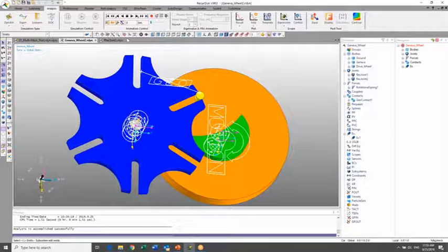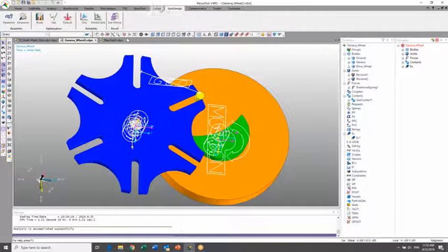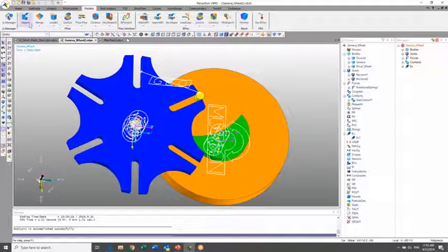There's a revolute joint and a spring, which is, I believe, just a damper at the moment. There's no spring force, it's just a damper. And so we want to go ahead and include all of those. We want to preserve the contact, preserve the joint, preserve the spring damper there, and mesh it. And so we're going to be doing something that was included in the previous version, which is this G Manager. So I'll click the G Manager.